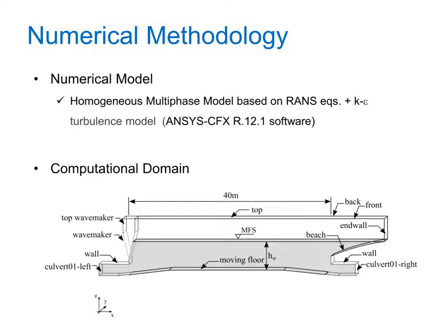We used a homogeneous multi-phase model based on Reynolds equations and the k-epsilon turbulence model. A two-dimensional cross-section of the basin was modeled and the expected lab conditions were simulated.